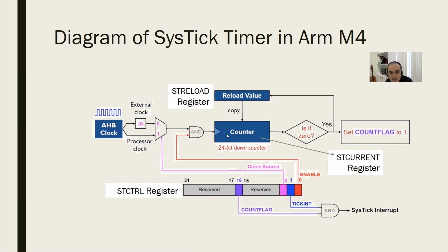So it is connected to a counter, which is decrementing. If it's enabled, it counts. Good. When it hits 0, because it counts downwards, it decrements. Is it 0? Yes. Then read this value in this register, which is also 24 bits. Just load it. So when it is 0, most probably there is a reset bit here, which is connected to this.